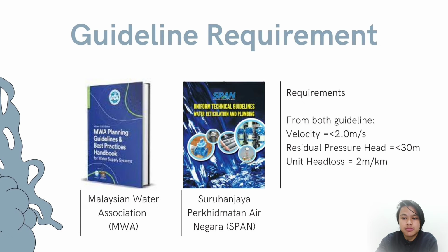Actually, when we first tried to design our water tank, we only had one water tank. However, the value of the residual pressure head became too large. Therefore, we needed to redesign our tank and decided to separate into two tanks in order to get the lower pressure head value. The other alternative would be to use a specialized material for the pipeline, but that will be at a higher cost, which is not in our favor.